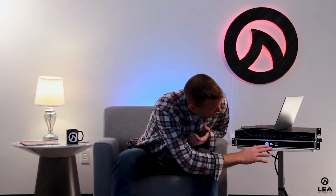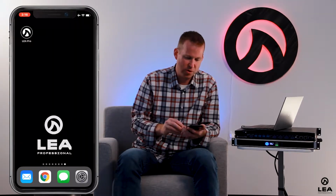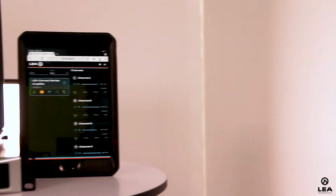So if I click this button on the amplifier here, the front of the amplifier shows your connection state. When you're not connected, it says disconnected. If you're connected via Cat5 connection or to the Wi-Fi, it'll tell you which connection mode you're in and then provide an IP address. So right now it says access point 704D-123 and gives me an IP address of 192.168.12.1.